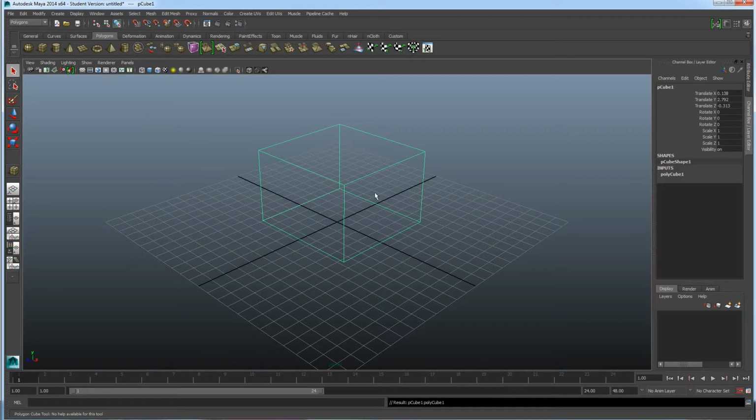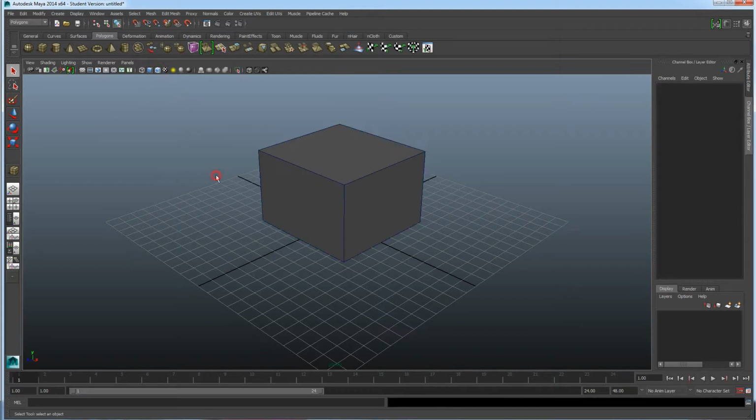Right now it's wireframe mode, and so that means we can see through it. If I switch out, and here's the wireframe mode icon, I can click on shaded mode, and it shades it, and then this wireframe unshaded, which we can't see at the moment, but if I click off of it, you can see it has a blue line on it, and if I uncheck that one, it takes that blue line off. This way you can see where all your polygons are on your finished object. And then a couple of settings, texture and lighting and such. So we can switch between these two if we need to see through the object.